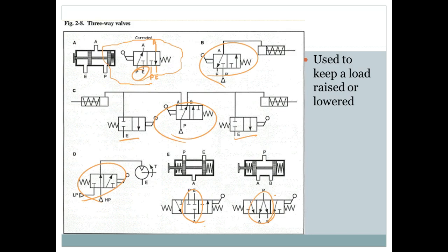So if you have a spring there... now if you have double operators, it's up to the system to determine which direction it is, right? What's your normal position? If you have 2 solenoids out there, what's the normal position? Well, it's whatever position they put that valve in to start off with. Normally, if we're running PLCs, we have what we call a reset routine.